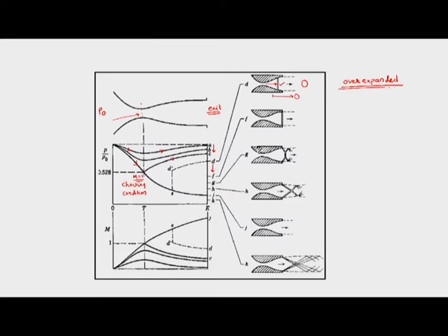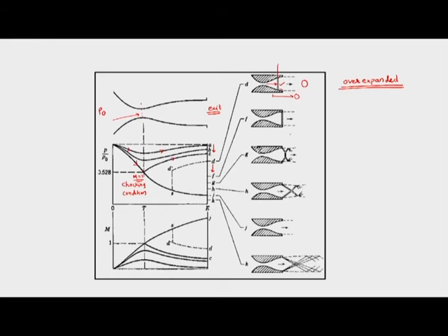Since the flow cannot have an over expansion condition, to limit its expansion there is a shock. After the shock, the flow would have a rise in pressure. There onwards we have the divergent section. This diverging section for the subsonic flow would treat as a diffuser, and then at the exit the flow will have the pressure as the exit pressure. So, this presence of the shock is going to make the pressure at the outlet similar to the pressure of the atmosphere.